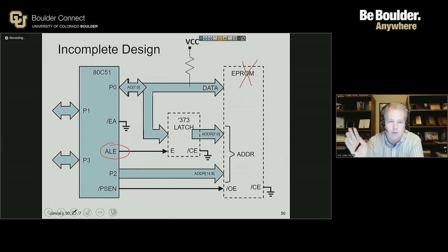I mean, there's all sorts of bits in that processor. Why would it change one of those 2? Floating pins can be anything unless P0 has its pins pulled low or pulled high with internal resistors. It could be anything, but again, doesn't it seem far-fetched that it would happen to be something that writes to one of those 2 bits out of all the bits it could possibly write to?